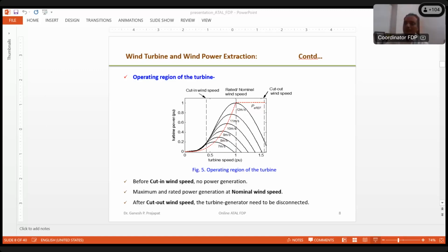So then the second one is one of the popular choices of generator for the generation of electrical power through wind, and this is the DFIG, or doubly fed induction generator. Actually this generator is something like this. Its stator is directly connected to the grid. So this is the grid, and here is, let's say, the transmission line in a simplified way. The stator is directly connected to the grid, while one interesting and important thing is that there are some connections available at the rotor of this generator also.